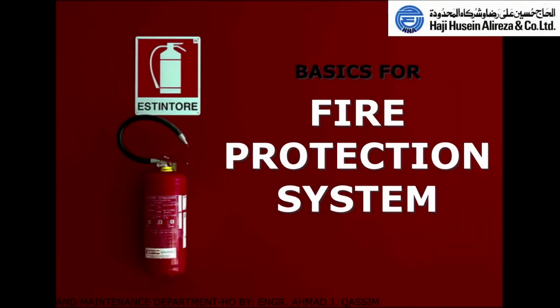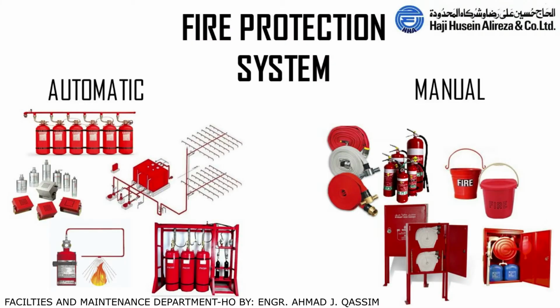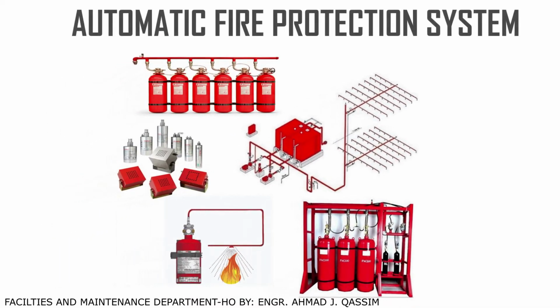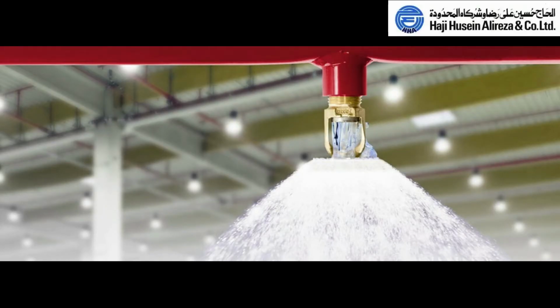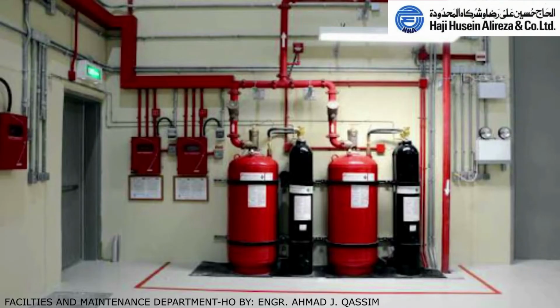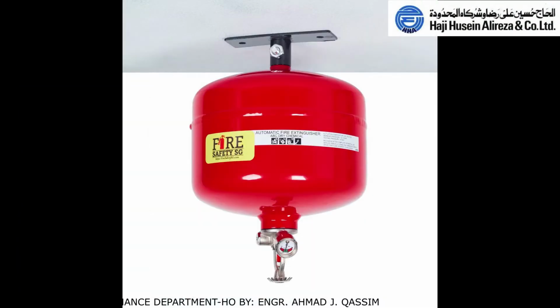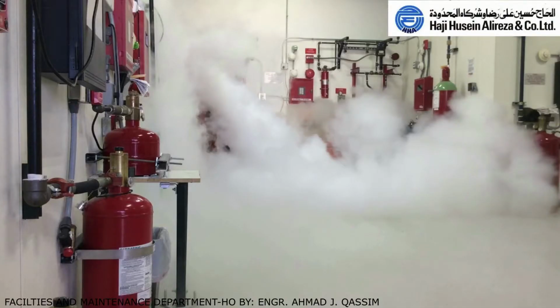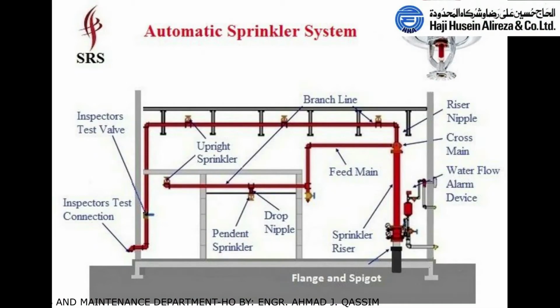Fire protection system. A fire protection system can be automatic or manual. An automatic system can be of different kinds depending upon the requirements. It can be a sprinkler system, FM200, Fire Pro, fire trace tube, dry chemical, carbon dioxide, Argonite and others. The most common for buildings is the automatic sprinkler system.